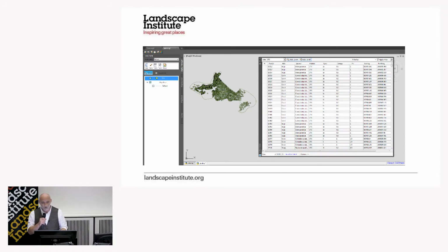So that what started off as abbreviations now contains all the species. It contains, quite importantly, where it is. It's Eastings and Northings. It's ultimate canopy size. It's the size of the tree pit that's needed. It's water content. It's how much water that plant's going to need over its lifetime, for the irrigation consultants.